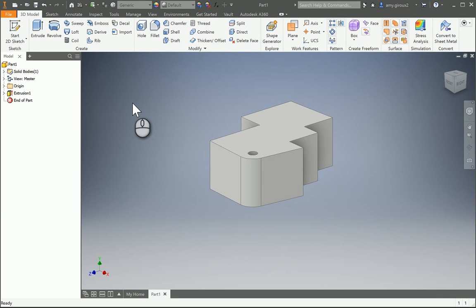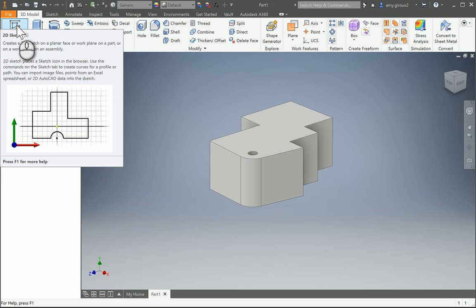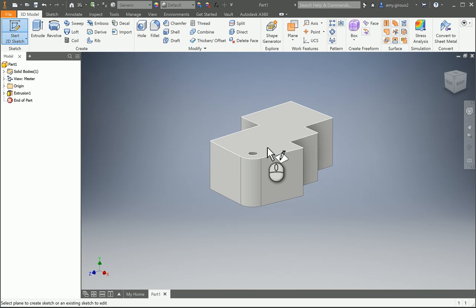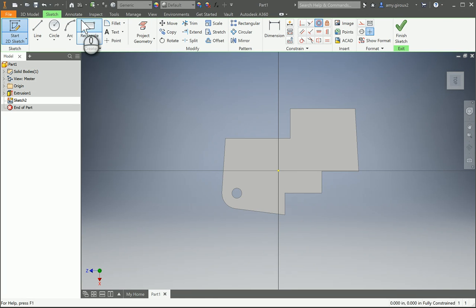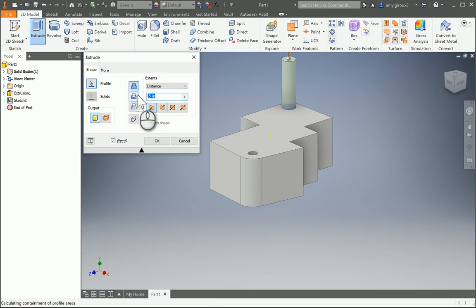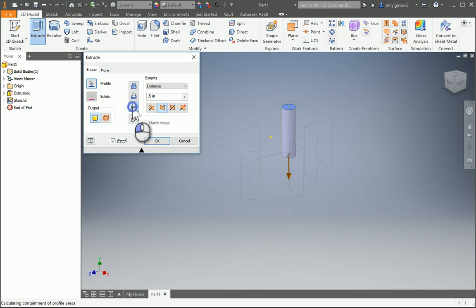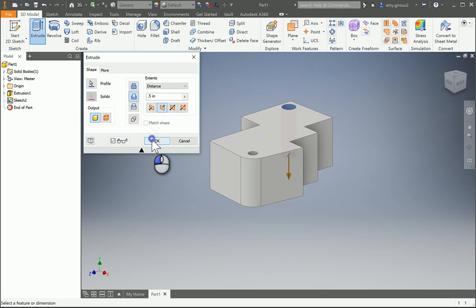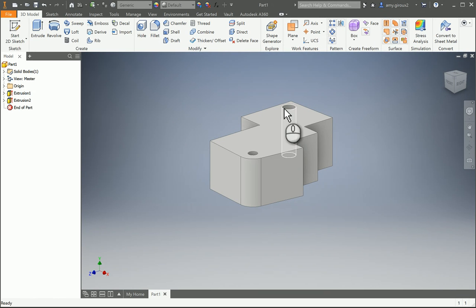With our part modeling, we also can do things with patterns. So let's say we want to create a sketch with a little hole through the center to add to our hole here. We're going to add a single sketch first with a single circle over in the corner on this side instead. If we create our sketch with our small circle, we can do a little bit more with our extrusions if we decide we'd like to cut them. We can choose different options with our extrusions. In this case, we're just going to cut. So we have a little feature that we can start to pattern out.